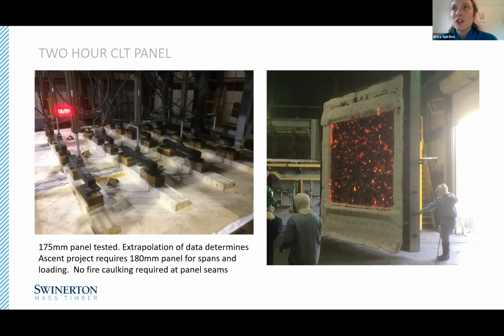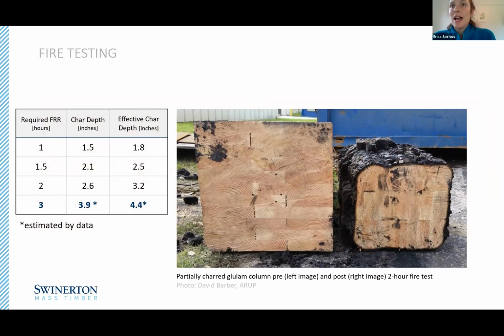And we made decisions early on to strategically encapsulate some of the glulam beams and columns. So when you expose a timber column in a fire rated structure, you have to upsize the member, and it's called sacrificial material. But basically the idea is that the timber could burn for 1 or 2, or in this case 3 hours, and you would still have enough cross-sectional area to withstand the weight of whatever load was being applied to that element. And in this case, the upsizing was significant for a 3-hour rated element. It's about 4.5 inches or so per exposed side.